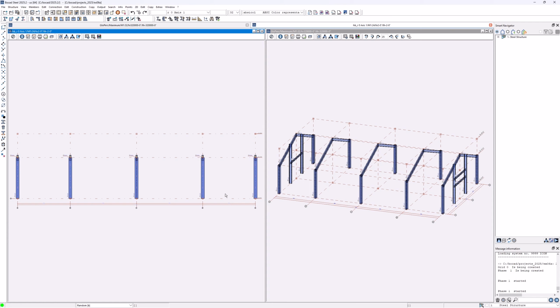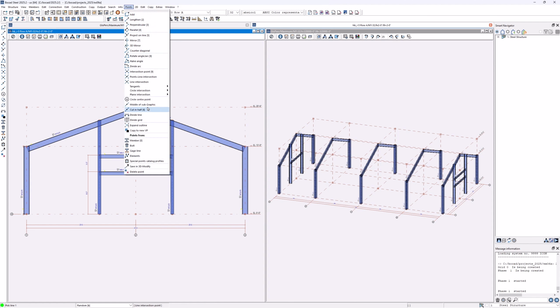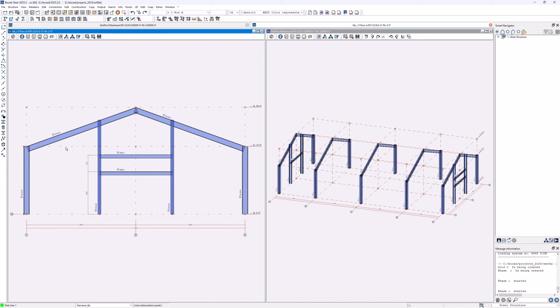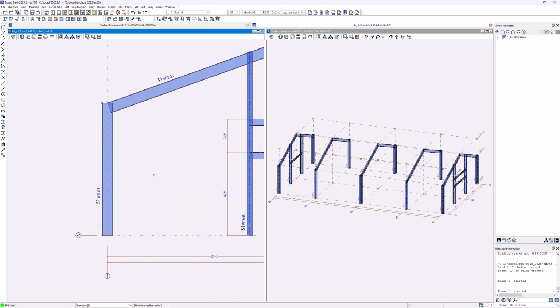So then I would have to still know half the height of that column and give an offset and so on. The other possibility is to say, well, I will need to figure out an equal division anyway. I might as well work with a couple of snapping references. So I will use points, line intersection between the axis or the grid line and the side of the column, flange of the column, and the other grid line. So I have this for now.